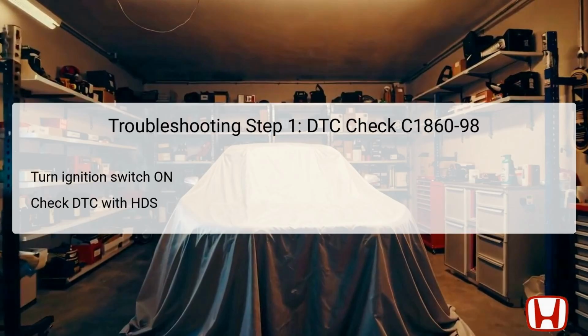The first step in diagnosing DTC C1860-98 involves checking the Diagnostic Trouble Codes (DTCs) using the Honda Diagnostic System (HDS). Begin by turning the ignition switch to the ON position, ensuring that the instrument panel lights up but the engine isn't started.